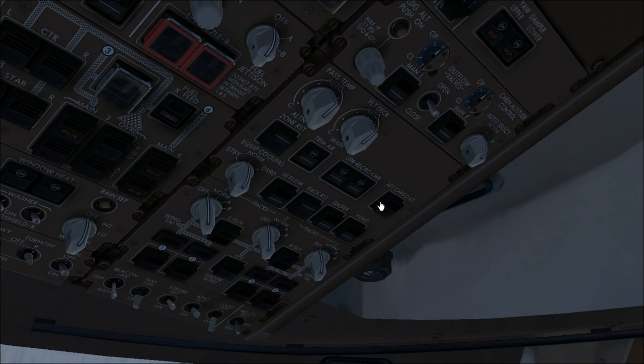After, cargo heat switch will be set off until after startup, because in this way some bleed air will be taken from the compressor, and this means less power and less air for the startup. Anyway, we will leave it off. Emergency equipment cooling selector is normal, of course. IFlow switch is off. Gasper switch and humidifier switch are both in on position to improve the air actually coming into the cabin for the people seated in the cabin.